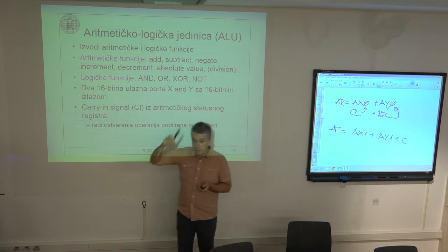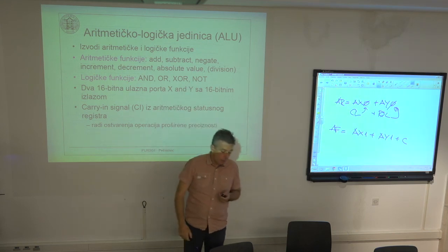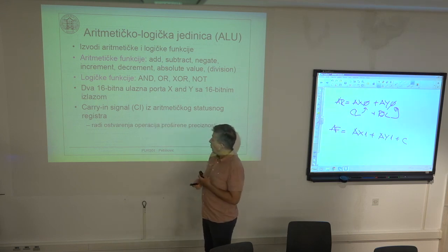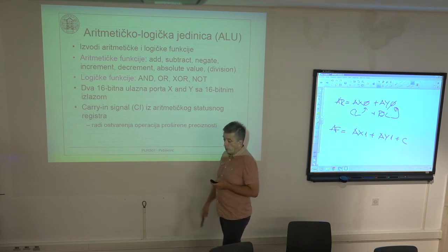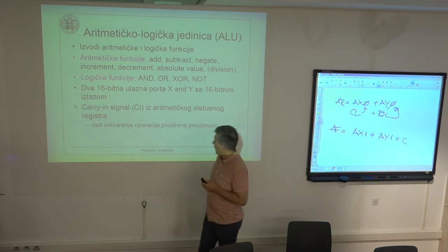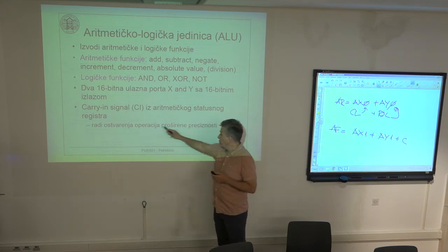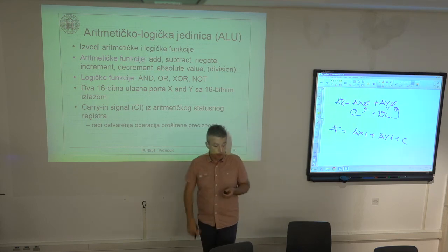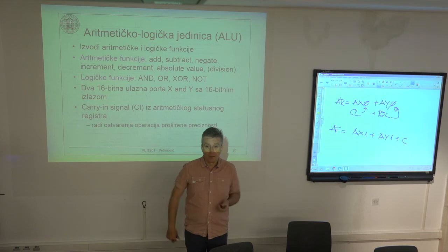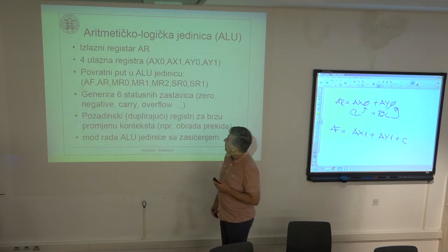As we said, it has left side and right side ports, X port and Y port. It has a carry in input, the carry in flag from the previous instruction. So the carry out of the preceding instruction is used as a carry in for the subsequent instruction. And it is used to implement extended precision arithmetic in a single precision data path.